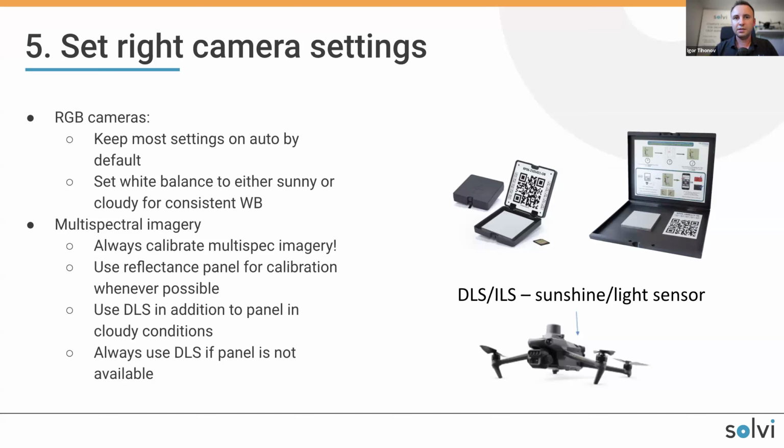Now, Mavic 3 doesn't ship with a panel, so I would recommend to always calibrate with DLS. Calibration with DLS might not be as consistent, but it's much better to calibrate with it than not calibrate at all. So that's it for these 5 tips for successful imagery collection.